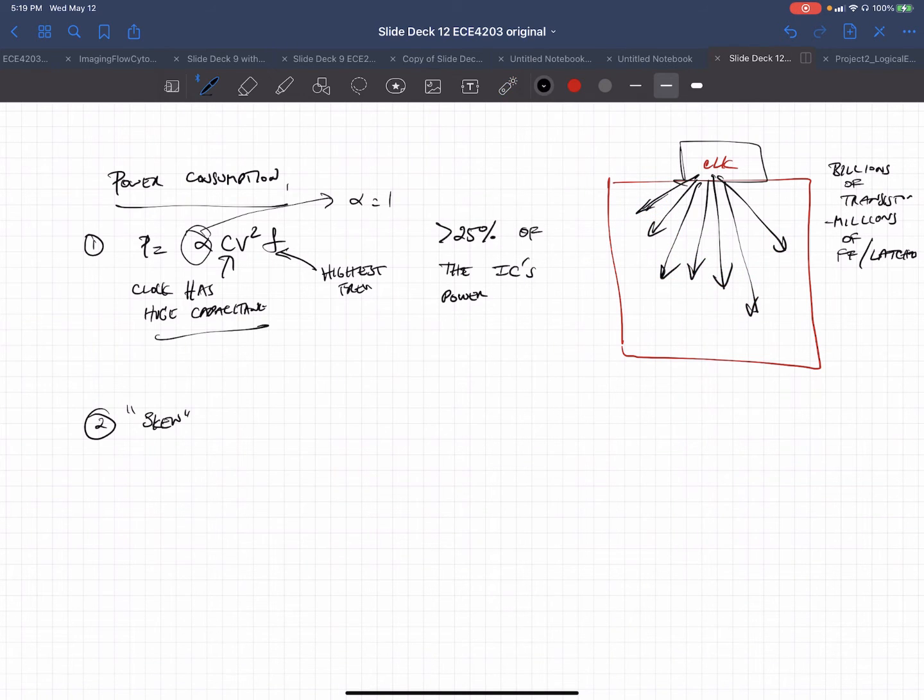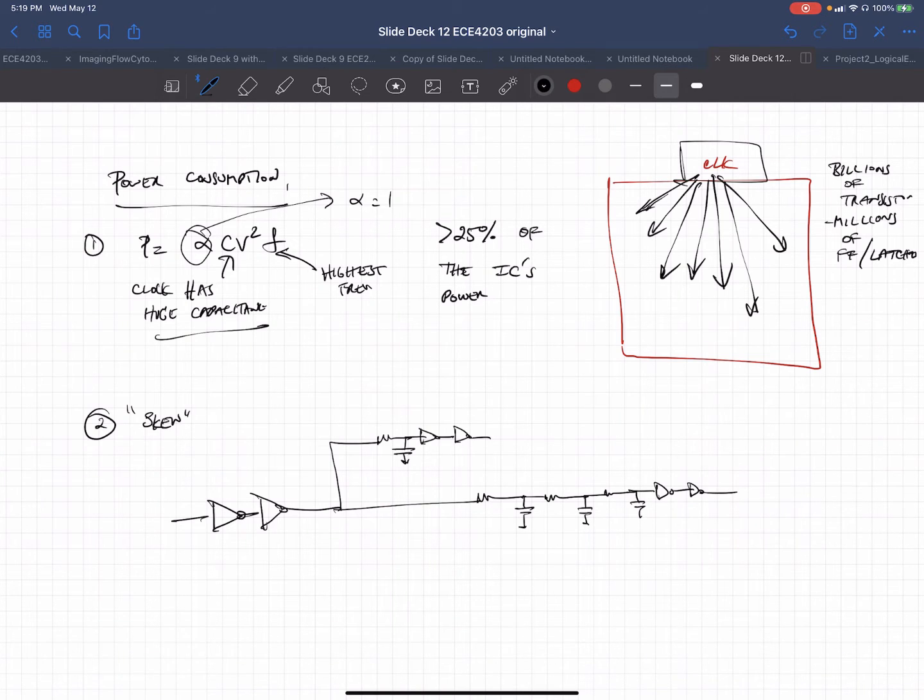But in reality, if you build your clock network, say you've got a bunch of buffers here, at some points there is a small delay, and there might be a much bigger delay if something's farther away from the source where you generated your clock. So the difference between these delays is called the clock skew.